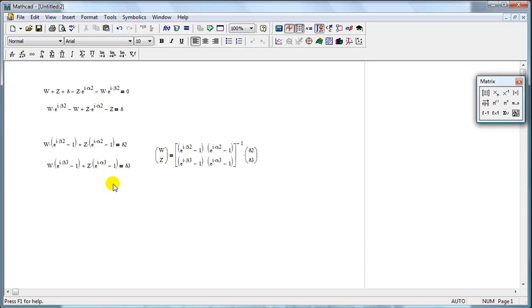Realize that for a 3-position problem, we can write this equation twice. This first version of the equation lets us travel from position 1 to 2. The second version of the equation lets us travel from position 1 to 3. And then these are two linear equations, two unknowns, using complex variables. The W's and Z's are the unknowns if we know the alphas and the betas, and we're going to pretend that we know all the alphas and the betas to make any progress on this. And if these are linear equations, they can be solved using linear techniques. So that's where we got to last time.